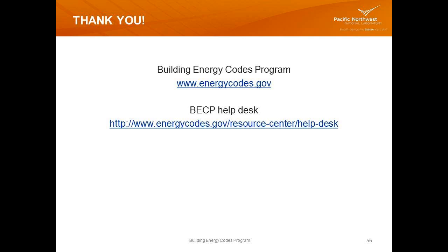How do I know what code to choose if the lookup gives both 90.1 and IECC versions? Okay, so in COMcheck, if you click on the code menu, there's a drop-down list of code options. If you don't know what code, out on energycodes.gov, we actually have state pages that show what energy code is adopted in each state. That's at the state level. So if you're in a home rule state, you might have adoption at the jurisdictional level. You'll need to check that. So you can go out and look at what the state adoption code is on the website.